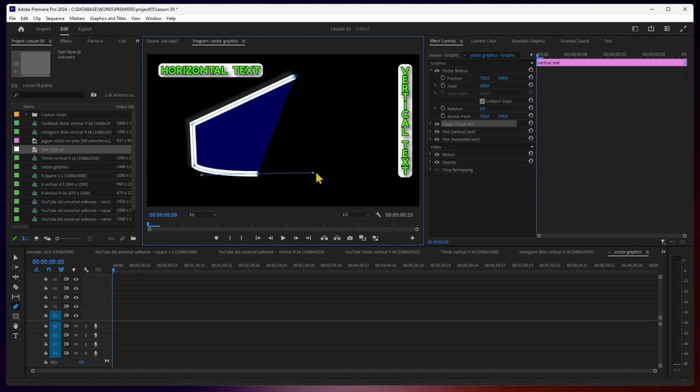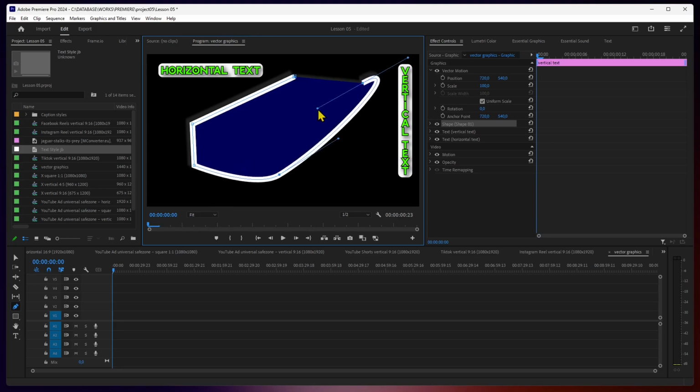If you click and drag, it's going to do a curve, which is called a Bezier, because it has a point or vertex, and then it also has handles that help you control the way this curve is created. Then I can continue, again, click and drag to curve, or just click once to do the corner, and then close this up right here.